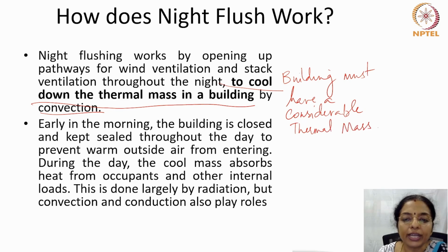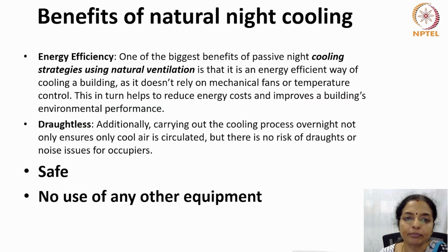Early in the morning, the building is closed and kept sealed throughout the day to prevent warm outside air from entering. During the day, the cool mass absorbs heat from occupants and other internal loads. This is done largely by radiation, but convection and conduction also play important roles.